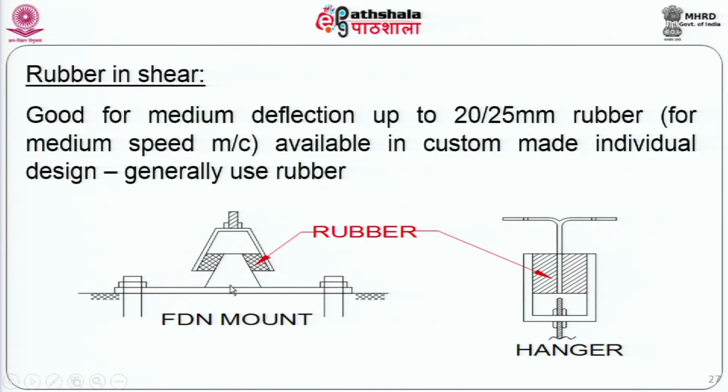In a foundation, it can take this shape. If it is for a ceiling suspended pipeline, it can take this shape. In other words, you can imagine this is a ceiling where these two holes permit you to screw in this rod onto the top. The rod is covered with rubber, which again supports a small hanger at the bottom. So, you notice that the vibrating equipment is not directly connected to the anchoring equipment. The only connection is through a tedious path. That means it transmits its vibration here, goes here, and through the rubber it gets transmitted to the support equipment.